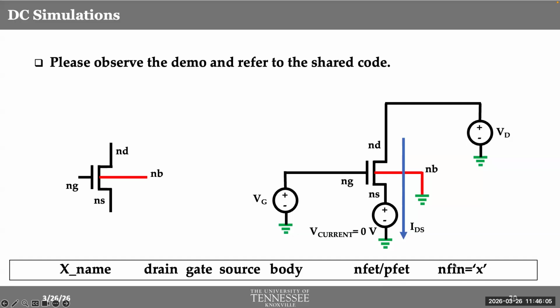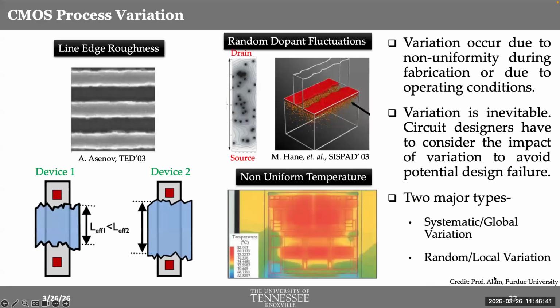And then this is the parameter list. Remember, I'm collaborating between Verilog and HSPICE here. I told you that in Verilog, you can define parameters and pass values to those parameters from other sources. Here is where I'm passing the values to the Verilog model. This is optional. If I don't write it, what will happen? Do you remember? Whatever was defined in the internal code of the Verilog model will be taken as the parameter if you don't pass any. There is a default, probably 1, I don't know. But if you pass something, this will override the default parameter. Similar here. We'll see these codes, and I will not go into these slides. You have seen this before.